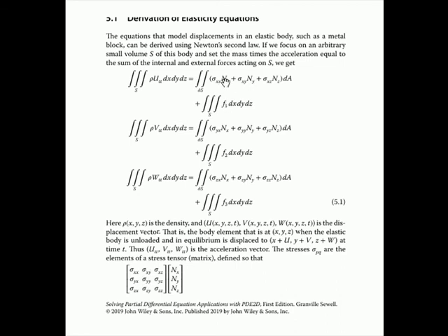So you integrate that over the boundary. There's your three components of the boundary force integrated over the boundary, and these three components will give you the net force of the rest of the material on the little piece S. Okay, well, then we use the divergence theorem. So this is the dot product of the first row of this matrix with the unit normal over the boundary. Then that's going to be equal to the divergence of that first row integrated over the whole region S.